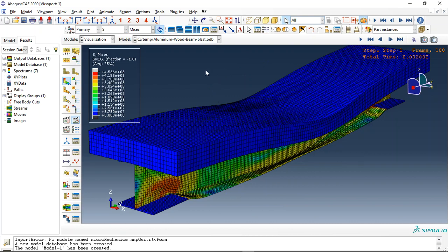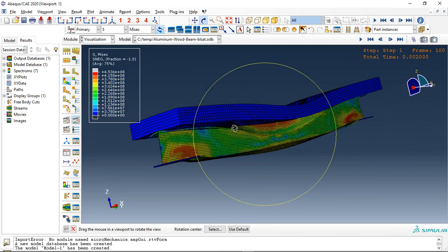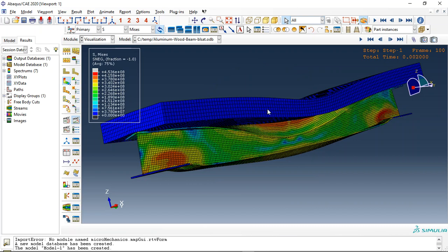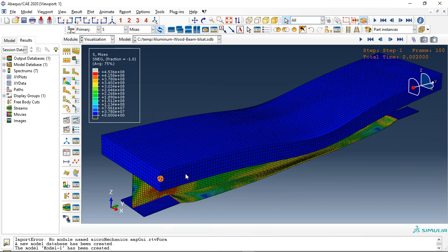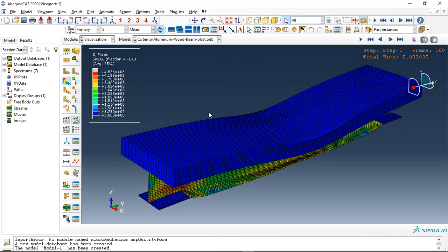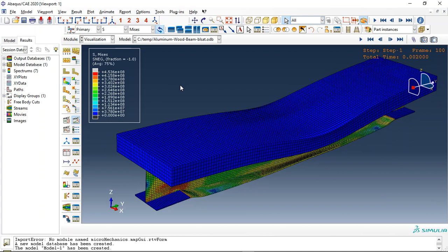Okay, so you can see here we use damage property to model the wood and aluminium, and we use connector as the connection between these two, and the air blast load is the conweb method. So here at the top layer of the wood we use compression data, in the bottom layer we use tension data, and the wood is the anisotropic material, so we should use the anisotropic property for that with the material orientation also.